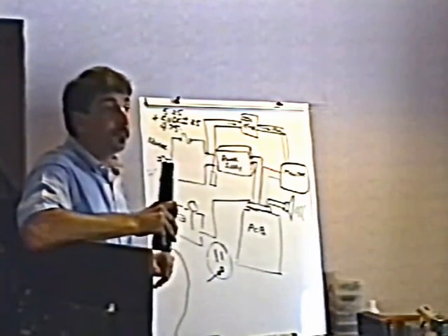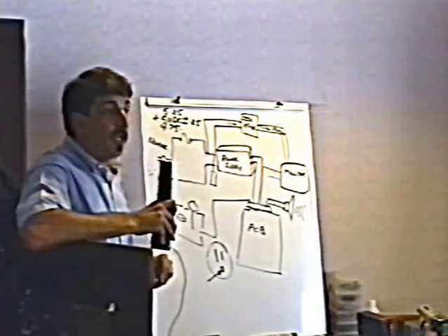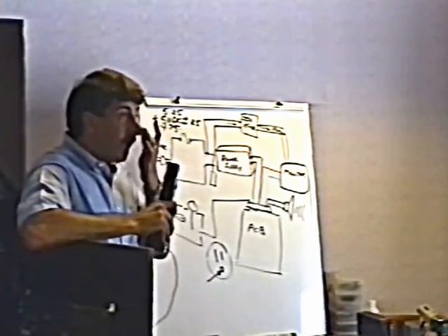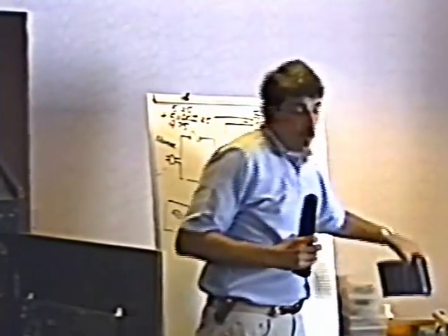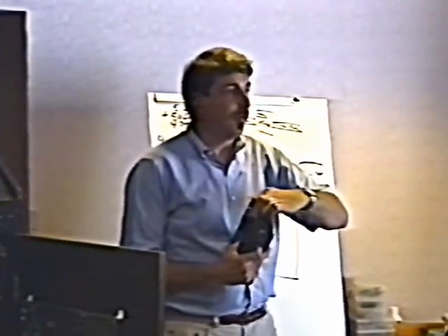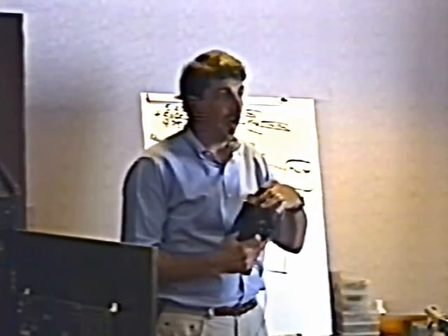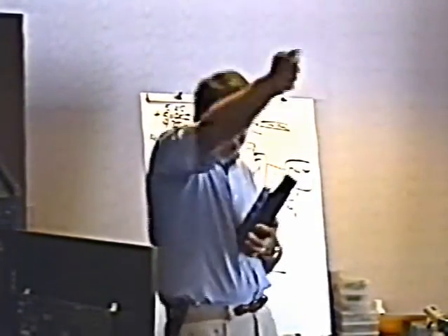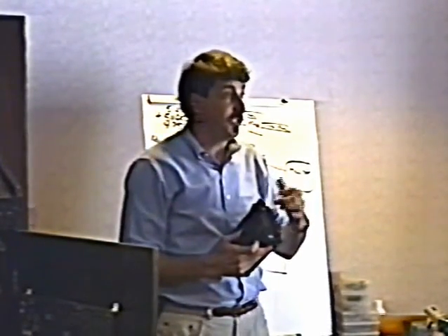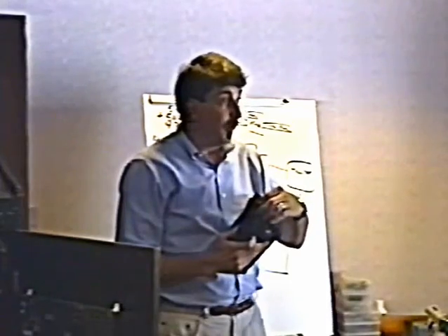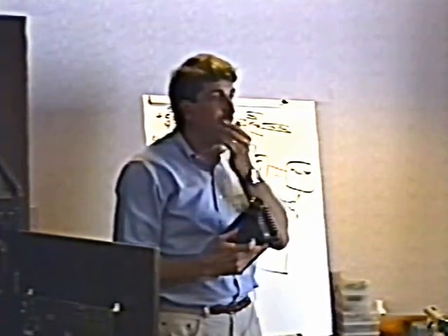Yeah, Ken. Is there any danger in adjusting that real fast too hard? You know, what if you're just way up high, and you go way too high? Yeah, that's bad. Most power supplies are designed so that you cannot, even at maximum, go dangerously high. But I wouldn't trust a power supply at all. You never go, hey, let's see how high it goes. With the meter connected, never adjust this without a meter connected, by the way. But with the meter connected, just slowly bring it up or down. I wouldn't mess around too much.